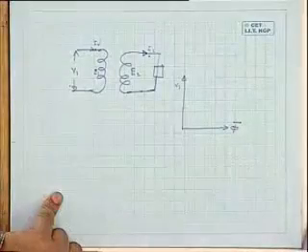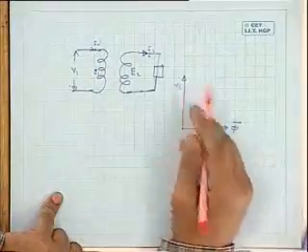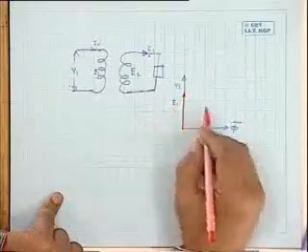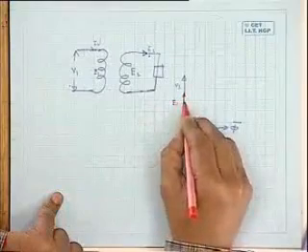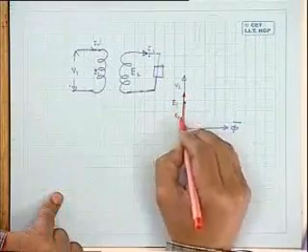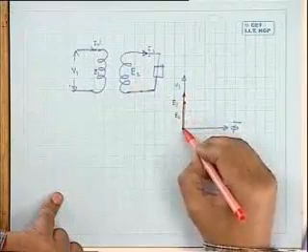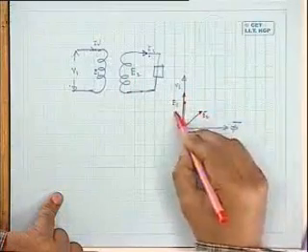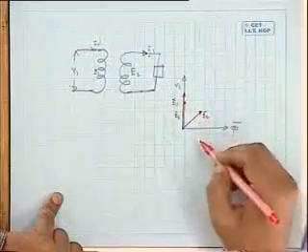So what they do is this, while drawing the phasor diagram, they will draw like this. B1 is there. Let us not forget about the direction of the power flow. As I see in the time domain, I will draw like this. This is V1. E1 I will draw like this, E1 straight. E2 will be like this, E2. Secondary current, suppose lagging power factor. You draw I2.